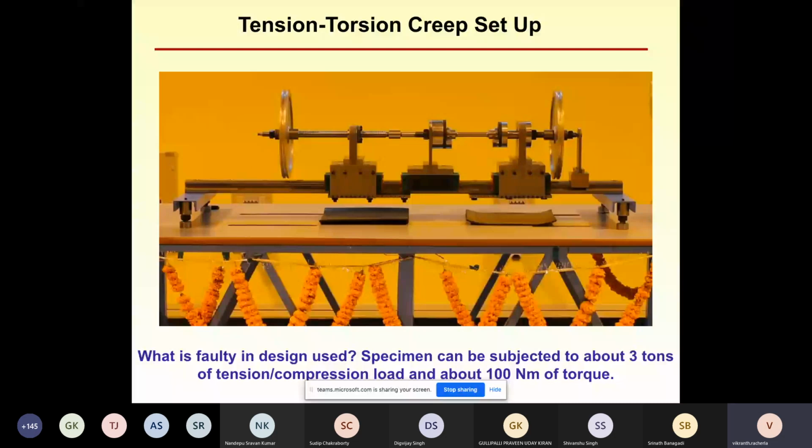The tolerance on this gauge is very small. It should not decrease by more than 0.5 mm, and it should not increase by more than 3 mm. But in quite a few, particularly locomotives, they were seeing that the gap between the wheels is increasing. They wanted us to study the problem and figure out what is the root cause.